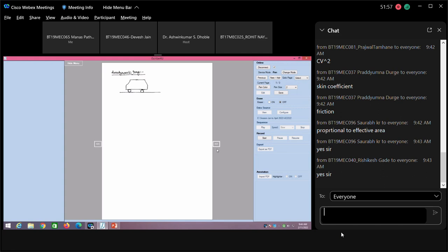Okay, now the air is moving from this side with, let us say, velocity v, and as you said, the vehicle velocity will be the same as the air velocity. If v is the velocity of the vehicle, then by the relative velocity concept the air will also have the same velocity, and you are saying that the drag force is equal to half CD A V square.